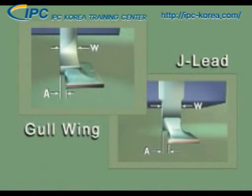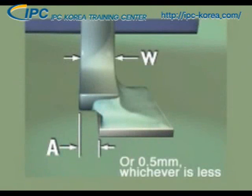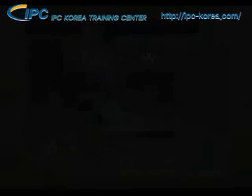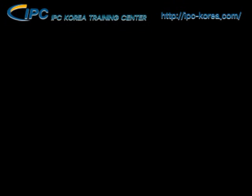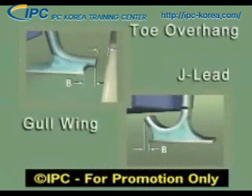J-leads and gull wings can also overhang the side of the land a maximum of 1/4 the width of the lead, or 0.5 millimeters, whichever is less for gull wings. The next parameter we'll examine is end overhang, or dimension B. This dimension is called toe overhang for J-lead and gull wing components.